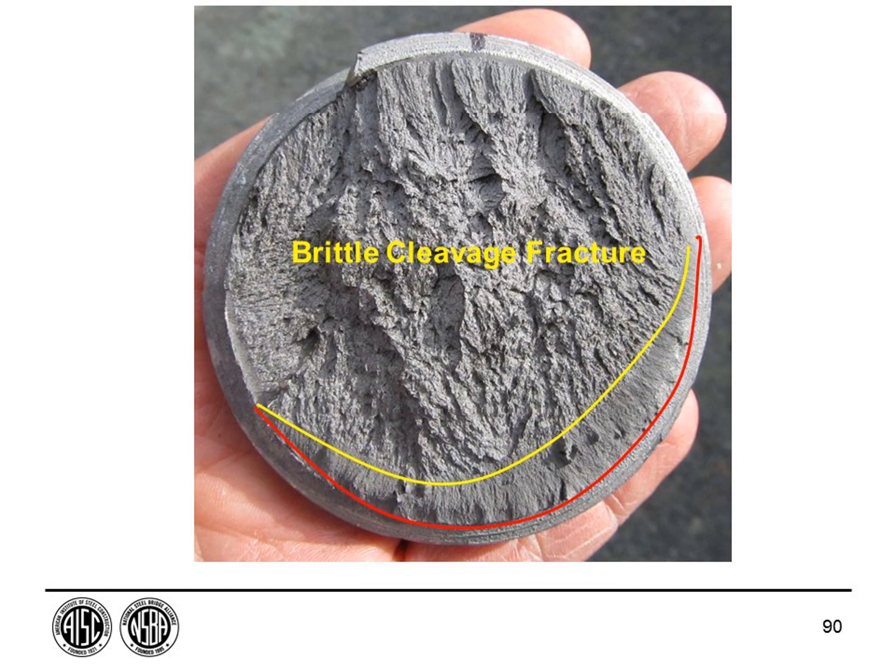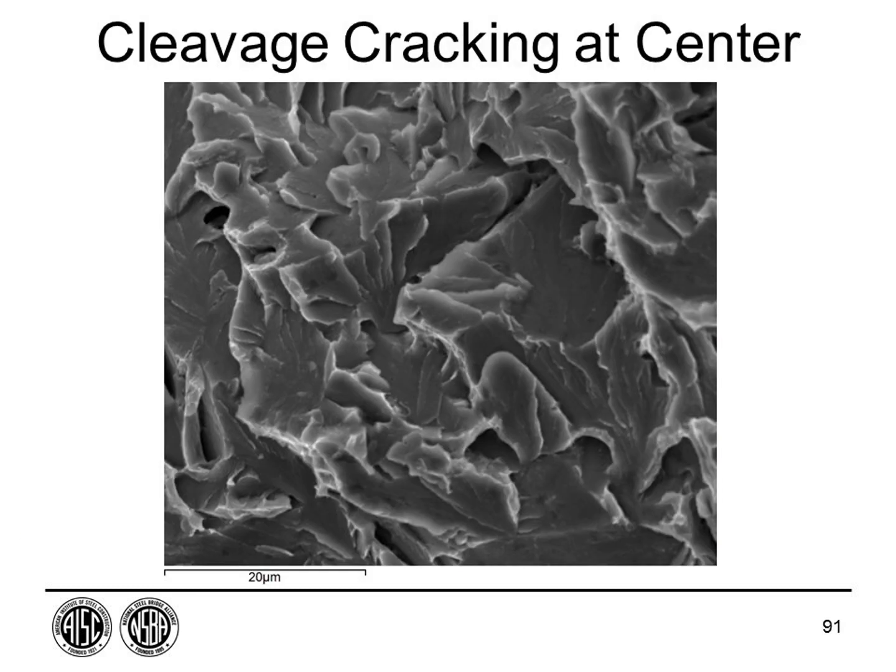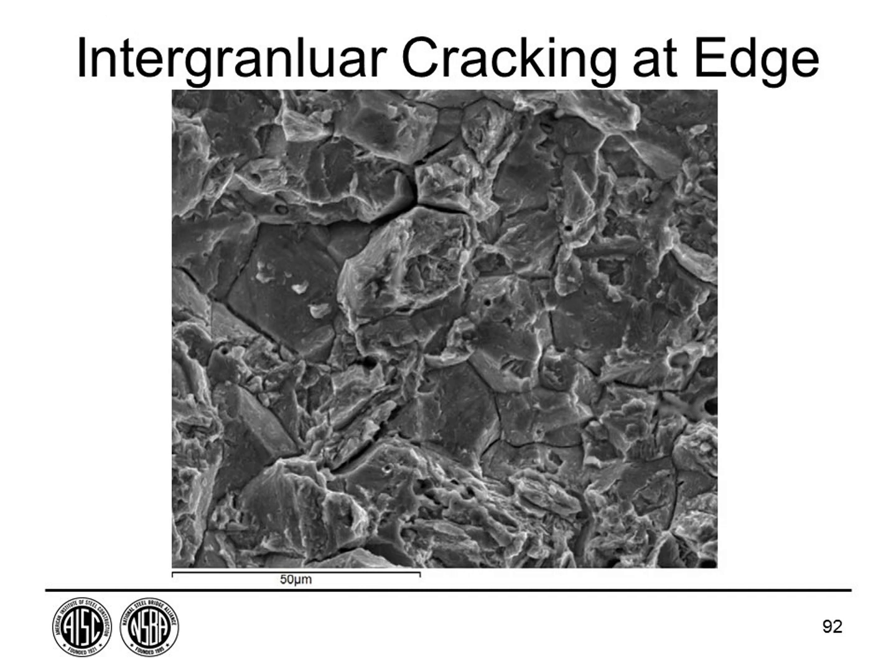When you look at the fracture surface, you had this area here, very flat, soft, smooth surface. This is an area where we had stress corrosion cracking, which is the cracking of the material under a static load. Then when the cracks got to this size, this was the critical crack size. We got a cleavage fracture across here. If you looked at the fracture surface in the electron microscope, this is what the cleavage fracture looks like. And if you go over to the smoother area, you see these fractures like this along grain boundaries, which is an indication of stress corrosion cracking or hydrogen-assisted stress corrosion cracking.